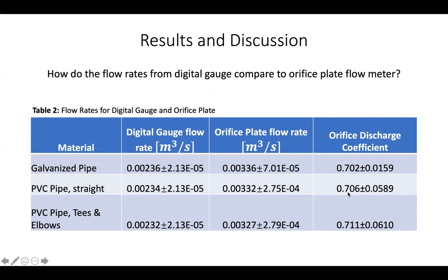And this allows us to conclude that the orifice plate is not recommended for use due to it neglecting these viscous effects, which are much lower when using a flow meter. The flow is therefore impacted far less with the digital flow meter, and this is instead recommended for use.